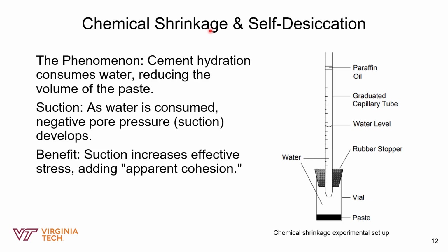And as I explained earlier, the cement hydration consumes the water, and since the backfill is sealed in the stope, the consumption just creates a vacuum or suction inside the pore pressure because air cannot easily get out of the fill. And so this suction pulls the tailings particles tightly together, and according to the principles of effective stress, this creates friction between particles.